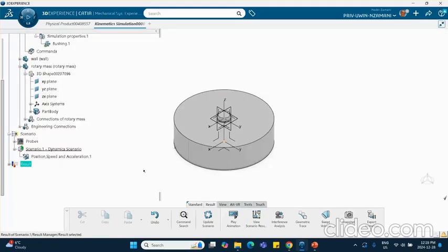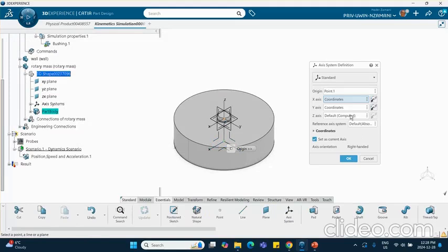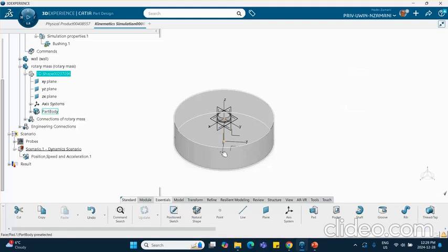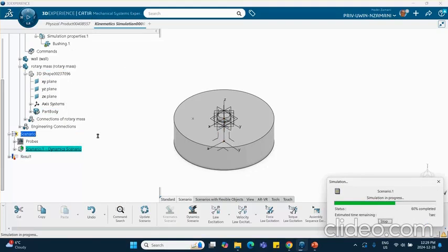To convince you one more time, let's double click on this. Let me rotate this thing by, I don't know, remember, this is small scale oscillation. The angle should not be very large, but I'll make it 40 degrees. Right click, rotation, about the Z axis. Maybe 40. You come up with the same period, or at least you should be close to it. It rotated by 40. Go back here and run it. Yep. And let's check the period.